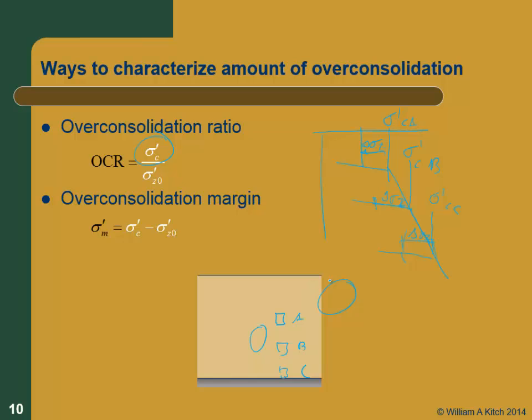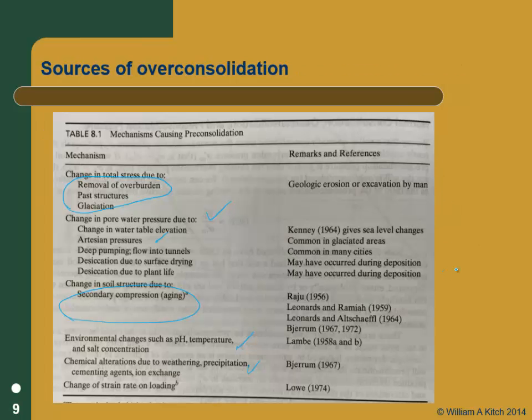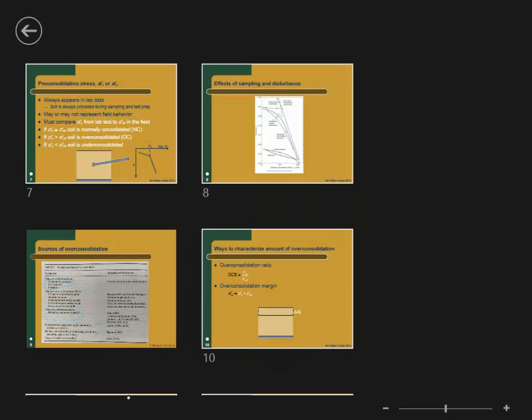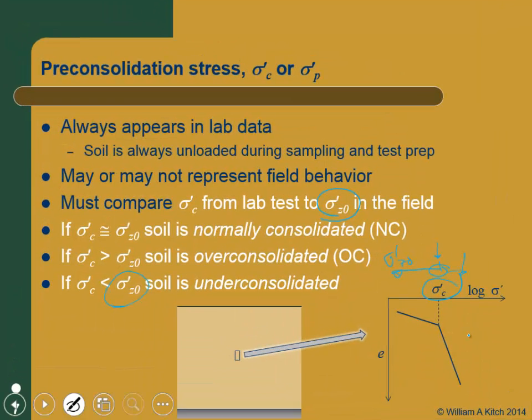Let me get back to one of my plots. All you know for sure is it's the point where those two lines intersect on a semi-log plot. Now, if that's an appropriate way to deal with the soil that you have, great, do it. And if your soil is strain hardening and it has a typical strain hardening curve of a soft clay or of a sand, then that semi-log curve can represent it pretty well.